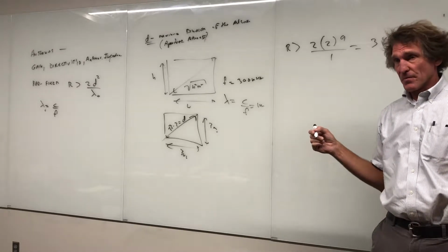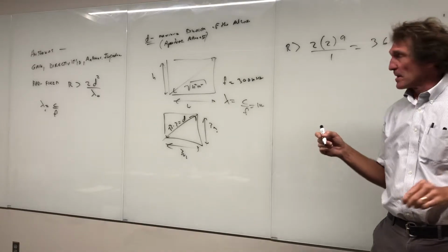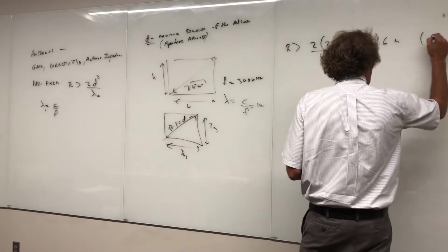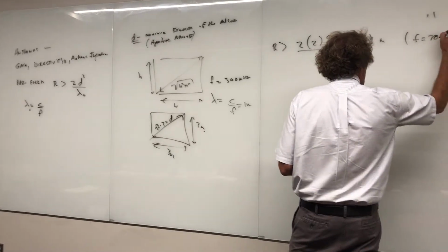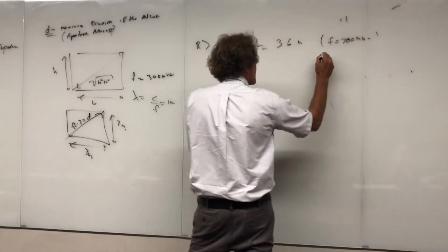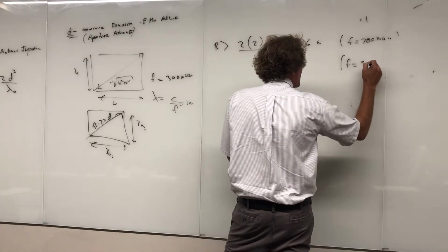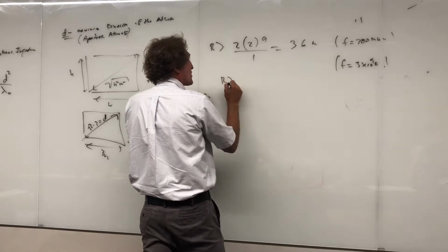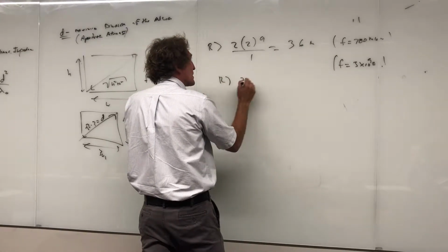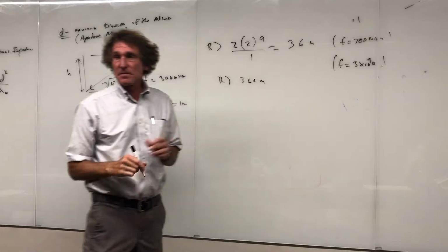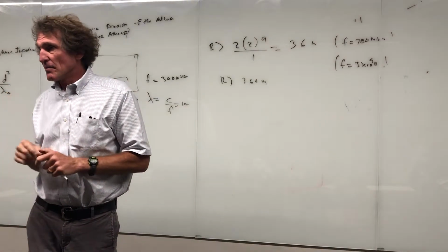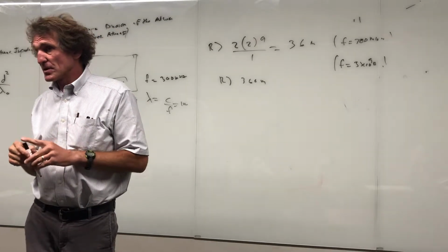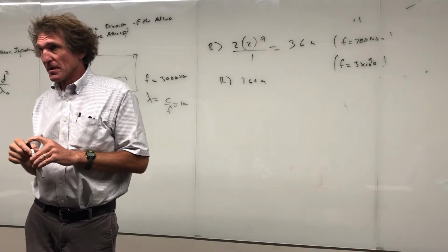It's a little different, by the way, for thin wire antennas, but that comes a little later. So what would it be? That's at f equals 300 megahertz, right? Well, what happens if f is equal to 3 gigahertz, 3 times 10 to the 9th hertz? Well, then I have to be at r greater than 360 meters, big difference. Follow me? Everybody see that? You have to be further and further away before you can assume far field effects.